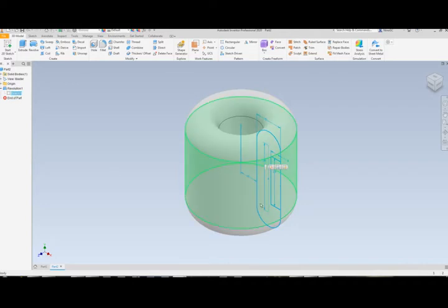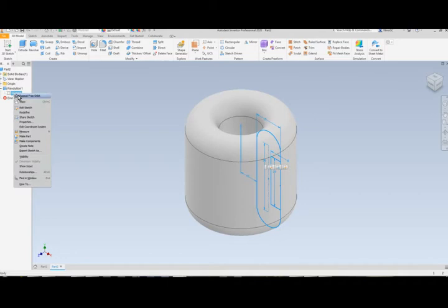Now when I click on sketch number 1, as you can see, it shows what the sketch is, and it also shows that the rectangle hasn't been consumed. So I need to have some way to use it. I can retrace it if need be. However, if I put my cursor over the sketch and go right mouse button, about a quarter of the way down there's something called Share Sketch. What Share Sketch does is that it brings the sketch back to the surface and allows me to then utilize any geometry that hasn't been consumed. So I'm just going to click on Share Sketch.